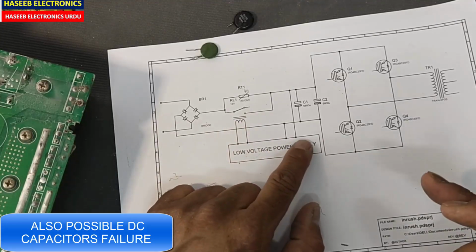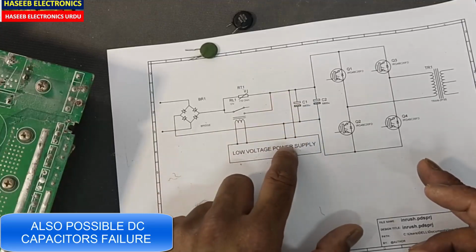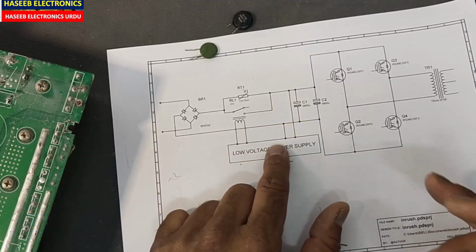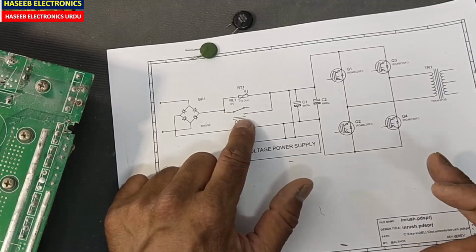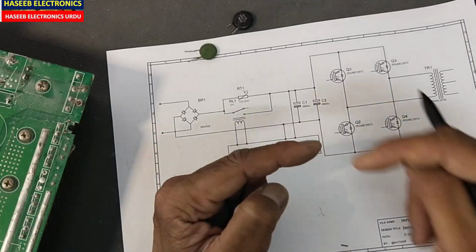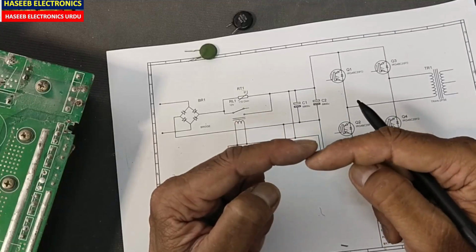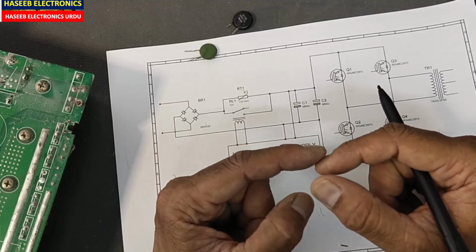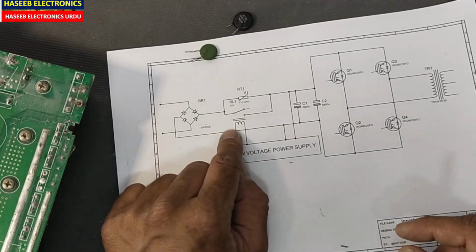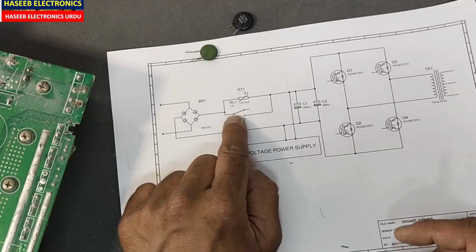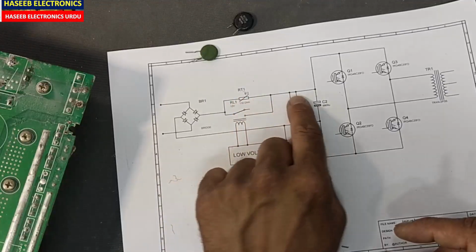The second problem: if this power supply's MOSFET is damaged, it will also cause a short circuit on the DC rail. The third problem, this relay, because this is a power relay, most of the time its points are making and breaking, and these make sparking. When it's sparking, its contact arms will be damaged. At that time, if this relay is turning on but its points are not closing the circuit, the current has to pass through this PTC.